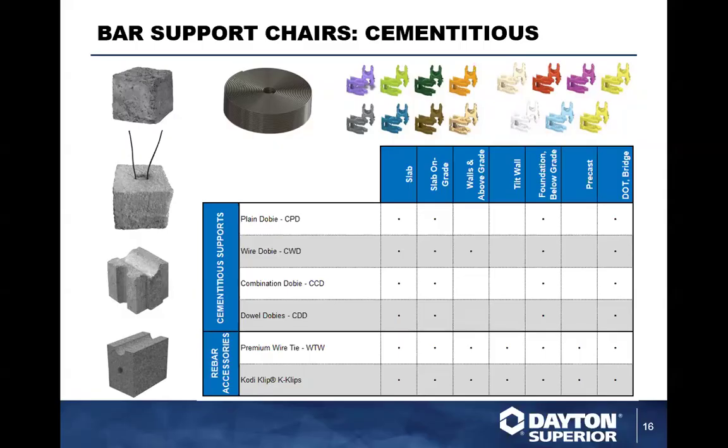He's gonna like it. You said that. There you go. And that'll take care of it, the new battery operated gun will do a 4 or 5 bar. We have air guns, pneumatic guns that will actually do 4, 5, and 3, 4, 5, and 6 rebar. And they are all color coded based off of rebar sizes and so forth. And it's a good option, especially if you're talking in the GFR market or the epoxy or even the stainless steel market.